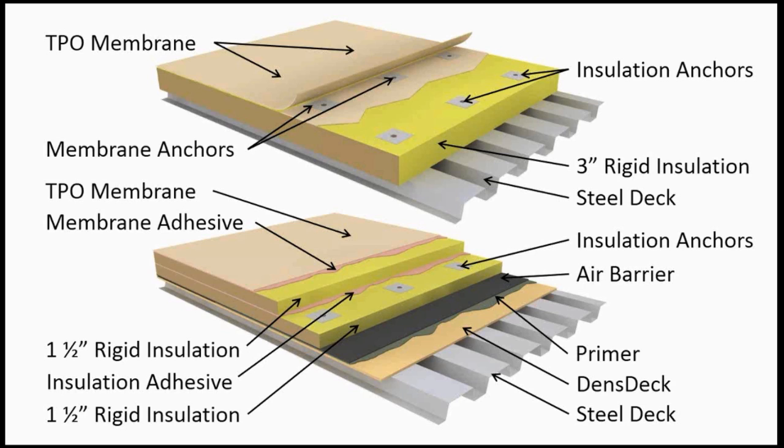It actually has the advantage of making it much easier to also see when you're putting in the insulation anchors at the edge of the repair area. You can see where the flutes are, and we really want to catch them on the upper part of the anchor if possible to sandwich that membrane and have the self-healing work for us as best as possible.